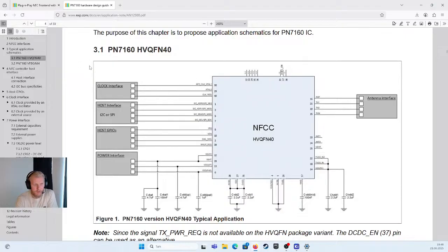Makes more sense to me. You see how you power the thing, then the signals coming to it, and the signals leaving it on the right side, the ground at the bottom, and other types of signals here and there based on where they're going. If they're going to the host, like the clock, just where it's logical and where you can make a nice schematic design without it being too hard to read.